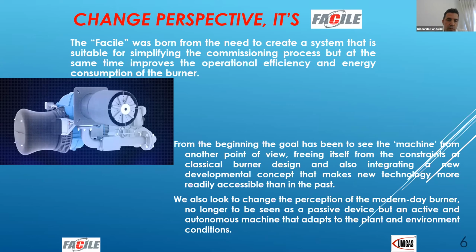efficiency of combustion during the operation without changing something on the plant. At the moment the technology can make it easy if you take some electronic control, but you have to use the O2 trim control from the chimney, for example.